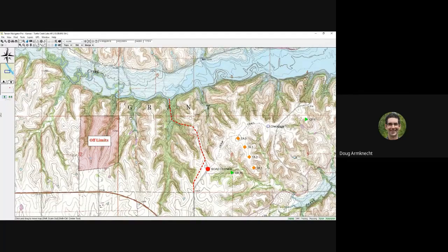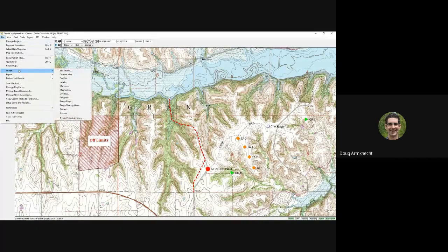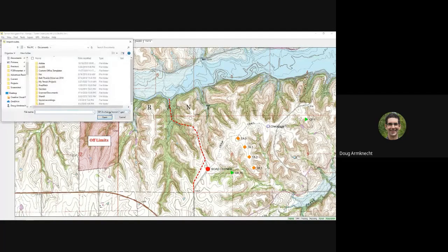All right, thanks, Ed. And I saw one more question come across. If you want to highlight a road or route you have stored in GPX, can you import it in that form? And you can do that. Let me just show you real quick how you would do that. Just go under File, Import. And in this case, I have a route in GPX format that I want to import. So I'll go to Import Routes. And we're in the GPX Exchange format.